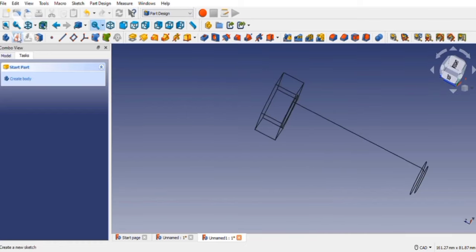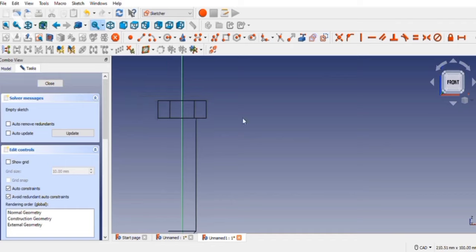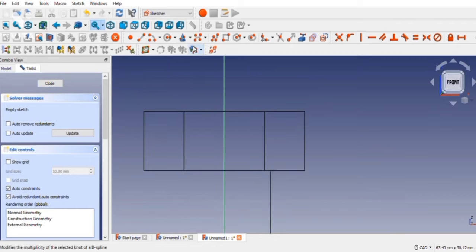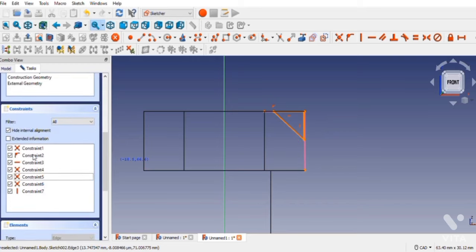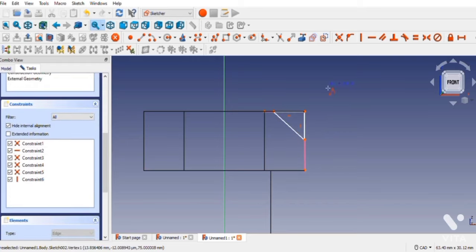it up to 10 mm, and I changed the view to the wire view, and then I started sketching on it on the XZ plane. I wanted to sketch a triangle in order to create a bolt-like structure on two edges. So I selected the two edges and I used a polyline tool to create a triangle, and then I made